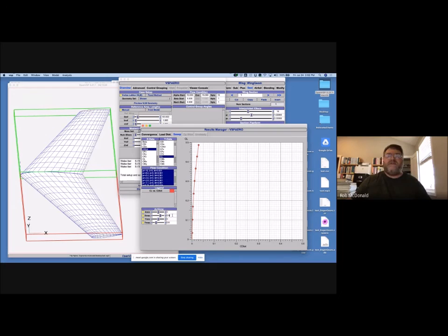But typically the axes will be super zoomed in because it looks better that way. But here they are. We've got the x-axis 10 times as big as the y-axis. Now, there's still something very important. If you draw a line from this origin and look for the point tangent to this curve, right about here, I think, that is the best L over D point. That is the maximum lift to drag ratio.